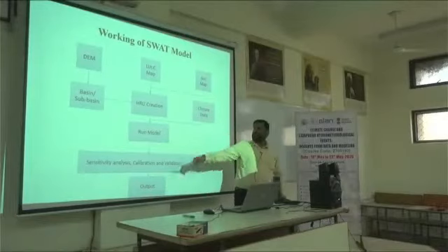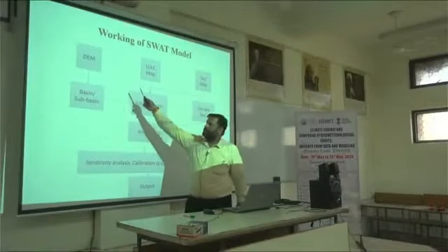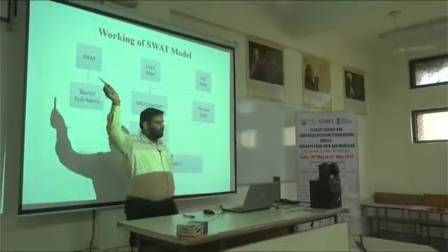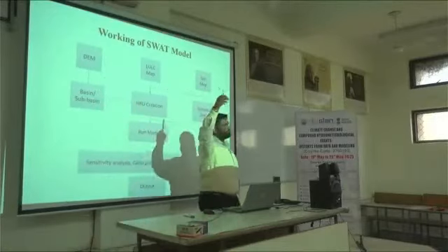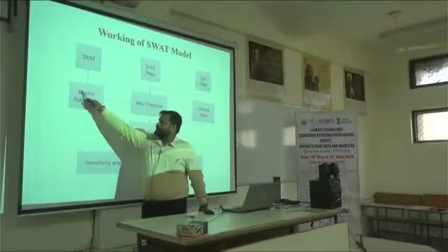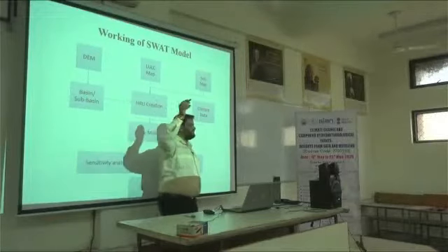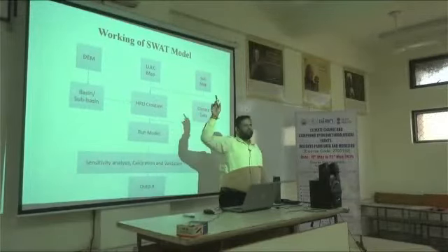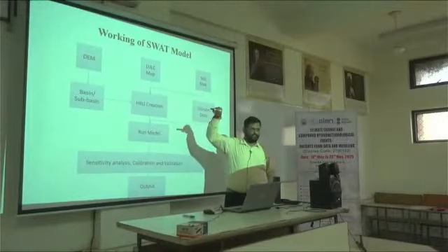Basically, from the digital elevation model, it will compute the slope, and based on the slope it will compute flow direction and flow accumulation. Ultimately it will create the basin boundary, and that basin boundary is further divided into sub-basins.